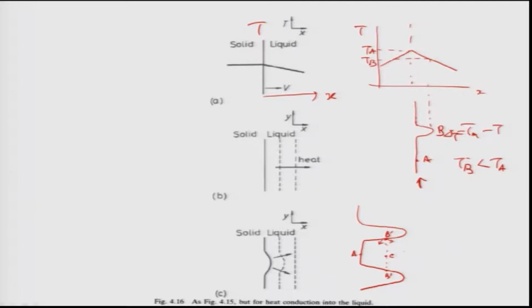and this latent heat, which gets evolved here because of further solidification, will heat up the liquid nearby point B. So, therefore, C, which is far away from point B prime, will be more undercooled. Here you can see these two are the point B prime, which are far away from these two positions, and because it is more undercooled, what will happen?